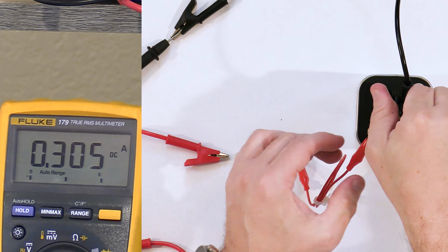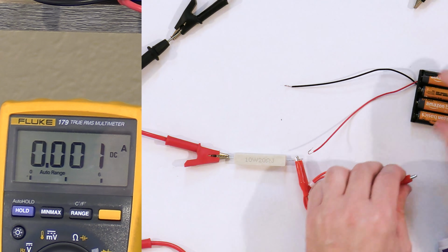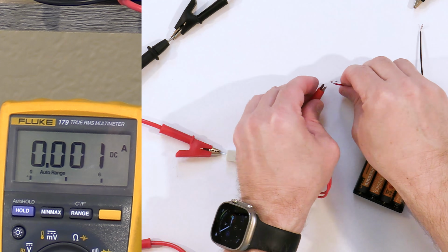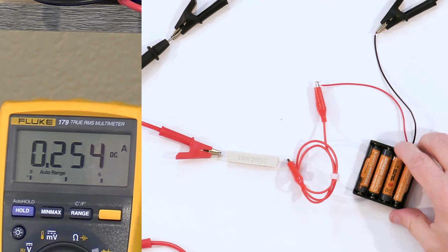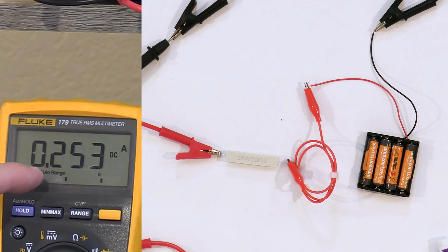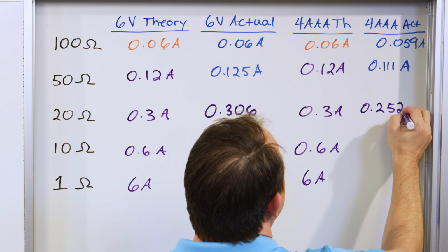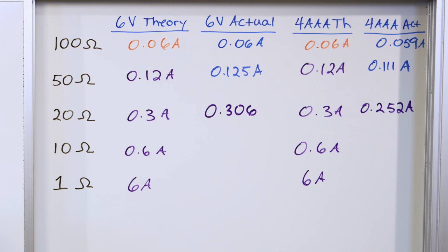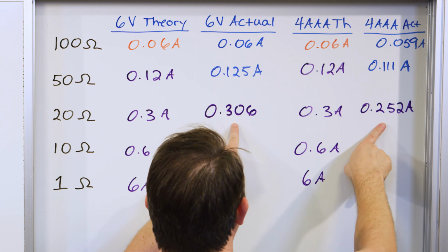All right, now I'm going to take the large battery off, put it aside. I'm going to grab the smaller battery right here, and we're going to see what it can supply. 0.3 amps, let's see, woo, that's a little different. It's not 0.3, 0.252. 0.252 amps. So clearly I'm going to disconnect it before I start draining the batteries down. I don't want to influence our experiment. But you can see that somewhere between here and here is when the break happened.